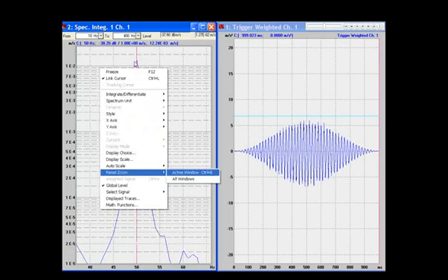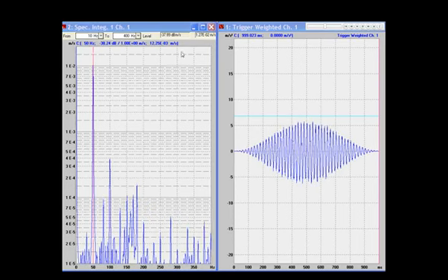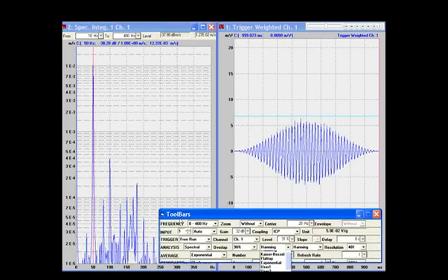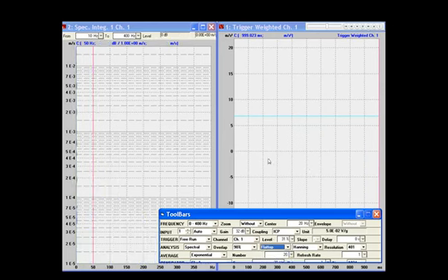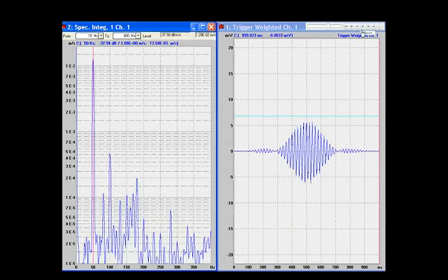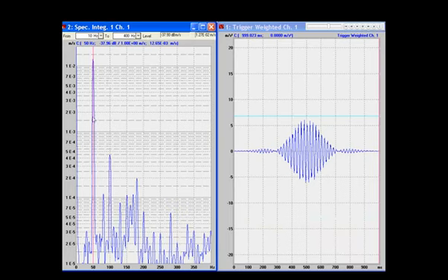We can see that the top of the peak had a triangular type of effect. If we go to flat top, what happens with flat top is a differently shaped window, and the spectrum gains some width, but the accuracy of our amplitude measurement is much better.